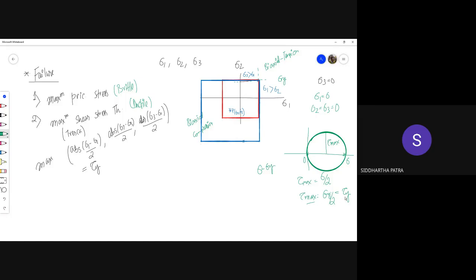That shows the failure occurs when sigma is sigma y, and then tau max is tau y, which gives us a relationship between sigma y and tau y, which is tau y equals 0.5 sigma y. This basically gives us this relation: the maximum of the three principal stresses, these being signed quantities, not unsigned, minus the minimum of the three is actually sigma y. Now, if you're in the first quadrant, the minimum is sigma 3, because both sigma 1 and sigma 2 are positive.